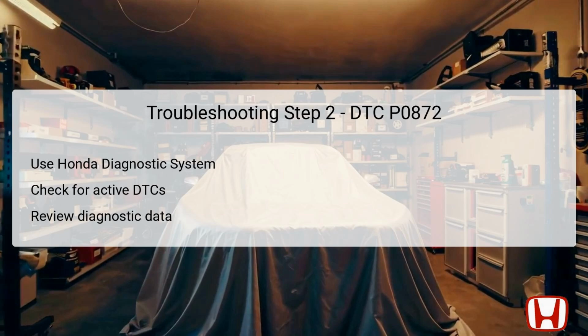This advanced diagnostic tool provides insights into multiple vehicle systems, pinpointing any persistent issues that might not be immediately apparent. It's critical to ensure there are no active codes that could influence the behavior of the transmission and related electronics. Review the diagnostic data carefully, specifically focusing on the transmission fluid pressure switch C input to the PCM. By scrutinizing these parameters, technicians can ascertain if the switch is providing valid feedback. Should there be inconsistencies or values that stray outside normal ranges, further investigative measures regarding the switch or PCM will be necessary before proceeding.